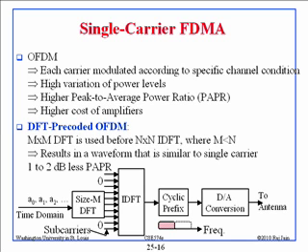And I know that because at some point I was trying to design some product. So the highest cost is the amplifier, and if you use this high PAPR waveform, then it will be even more expensive, because the amplifier has to operate linearly in this range as opposed to in this range, right? So how do we reduce the PAPR? We use single carrier. With single carrier, the peak to average is very small.